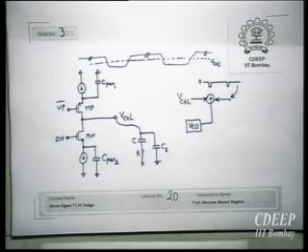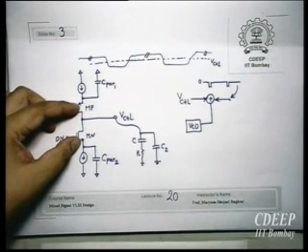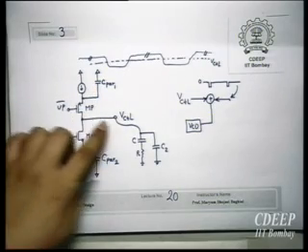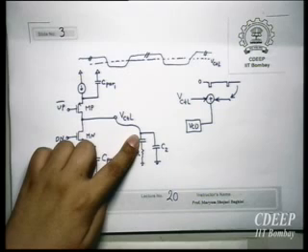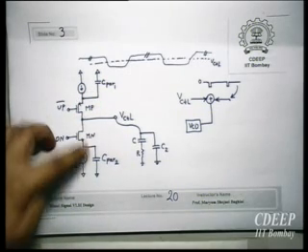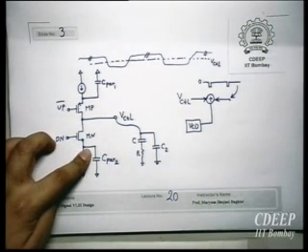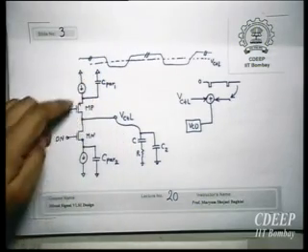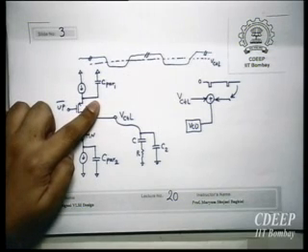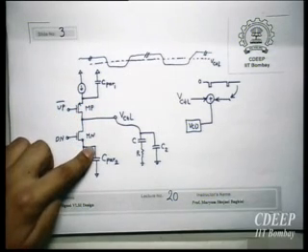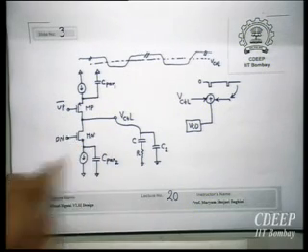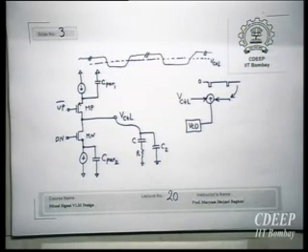Now when they are on in a steady state, what happens is, suddenly you are connecting these two capacitors to this output voltage, right, and these two capacitors had 0 charge. Now they have to charge to the voltage. This was 0, means that this effectively has settled at VDD, this node has settled at ground, and this node has settled at VCTL. Now you switch on both of them when those narrow pulses are generated.